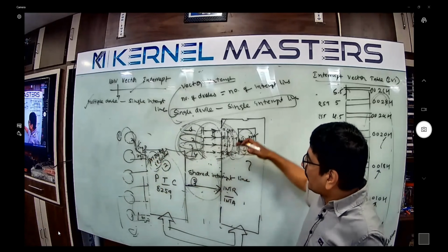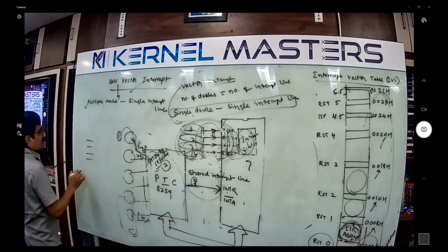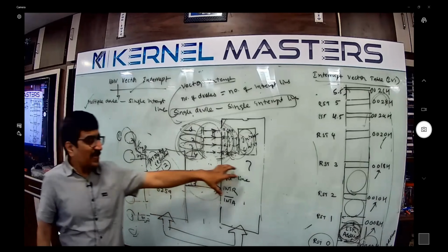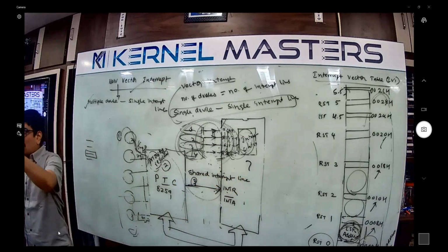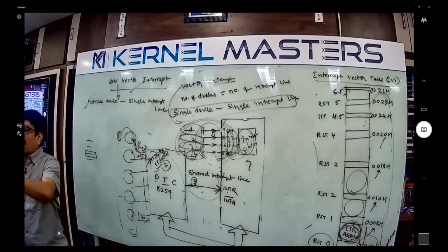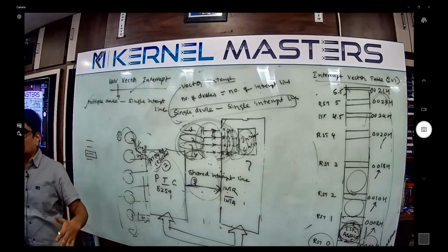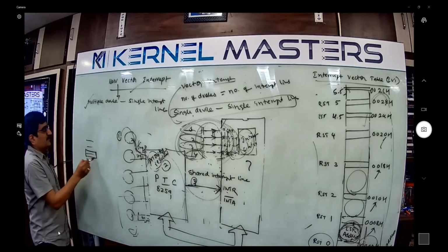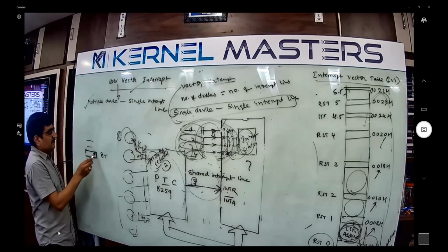Now, whenever the microprocessor is executing some instruction, suddenly an interrupt occurs. The interrupt occurs in the time of some instruction or program execution, but the microprocessor does not handle the interrupt immediately. It takes some time to complete execution of the instruction. For example, say this instruction takes 8 cycles.